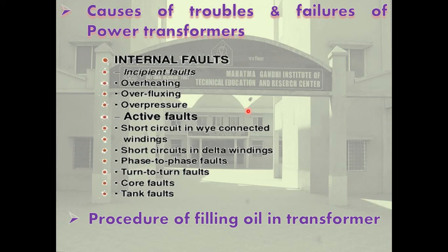Okay. Second is sustained higher voltage on primary resulting in overheating of core due to overfluxing. Causes are poor voltage control of power system. Use shunt reactors and tap changing transformers to control busbar voltage within specified limit. The transformer can fail due to sustained overvoltage, so provide overfluxing protection and overvoltage protection for busbar.